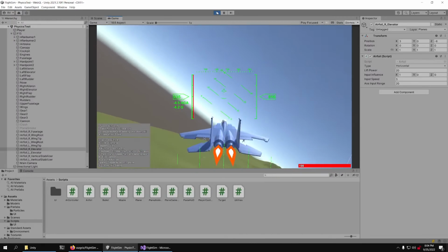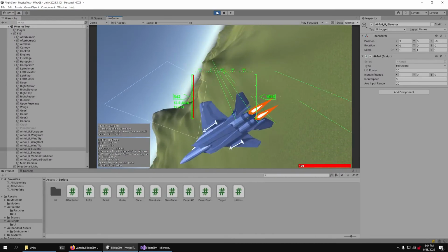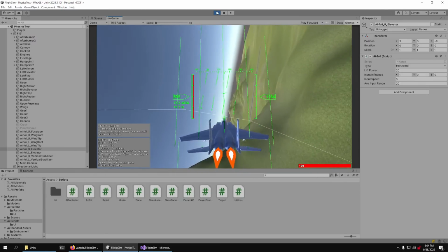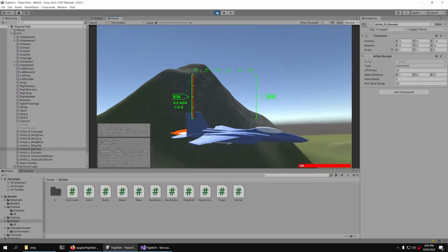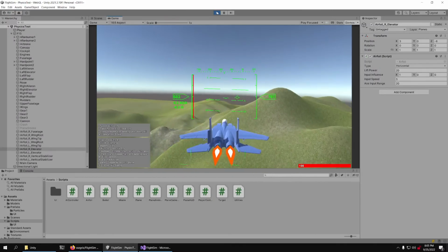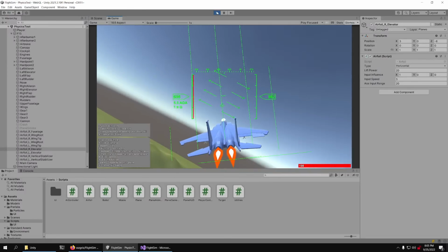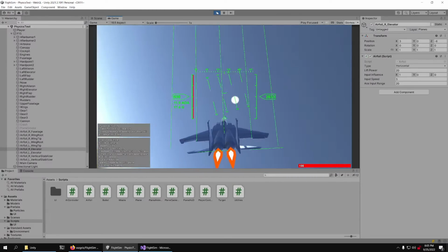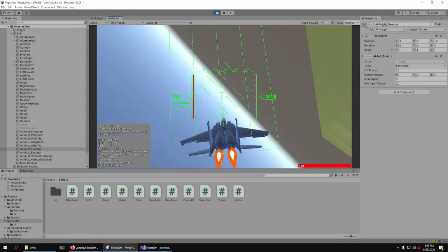Oh, you know what it is? I can't really change the roll whenever I'm pitching because the wings are loaded. I need to actually unload the wings before I can change the roll direction. Okay, so that's a property I wasn't actually expecting to handle, but it does work correctly now. So I need to release the pitch input before I can start rolling, which is something you have to worry about on real planes as well.